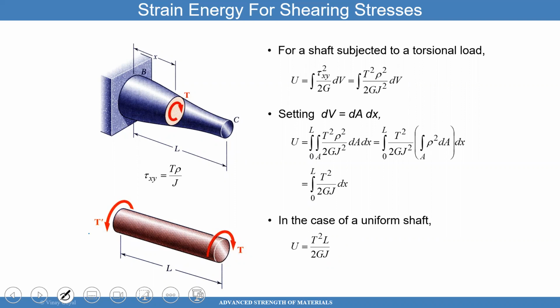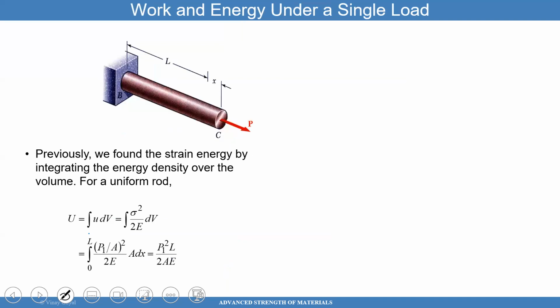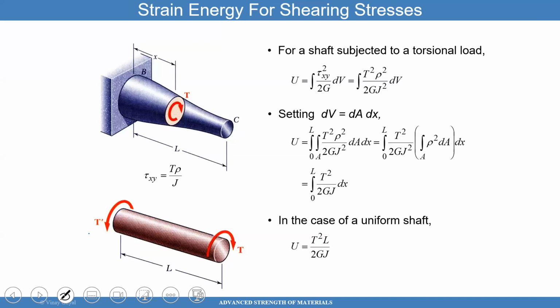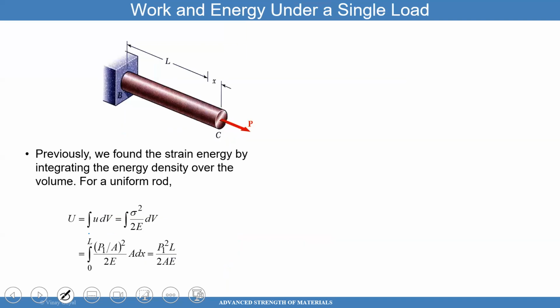You can superimpose, beautifully said, 20 points for you. You can superimpose different solutions for different problems, as long as everything is linear. And when you add them up, the stress does not exceed the yield of the material. Everything can be added as long as you're below the yield of the material. Okay, please. So if there's a case where it's like torsion and a load applied, you just add up? Yep, I'll show you that. I have an example. Excellent.